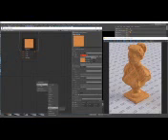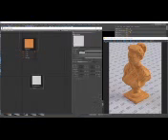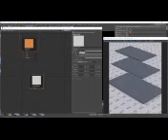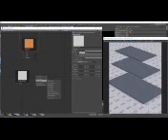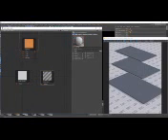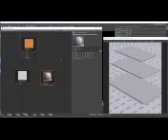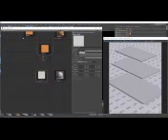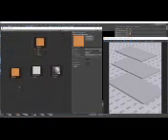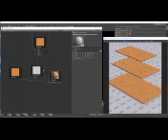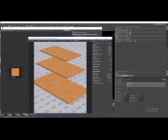For this, let's hide the sculpture and unhide these planks. Create a new Corona material and assign it to them. Load the same wood parquet texture and connect it to the diffuse color input. Also select the texture tag and decrease its tiling to 0.2 and 0.2.